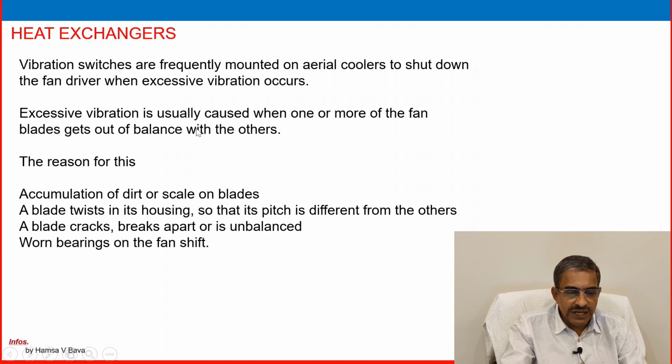Excessive vibration is usually caused when one or more of the fan blades get out of balance with the others. The reasons are accumulation of dirt or scale on a blade, a blade twisted in its housing so that its pitch is different from the others, a blade cracked, broken apart or unbalanced, or worn bearings on the fan shaft.